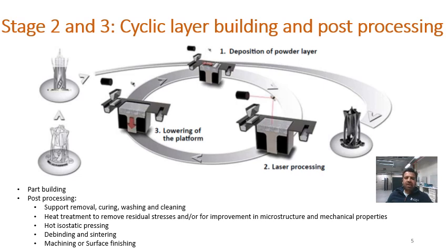Nowadays, some indirect printing techniques for metals and ceramics are being industrialized, and these technologies use a binder material to build the parts, and this binder shall be debinded before the firing step to achieve high densities. These AM methods have a lot of freedom to produce complex shape parts.